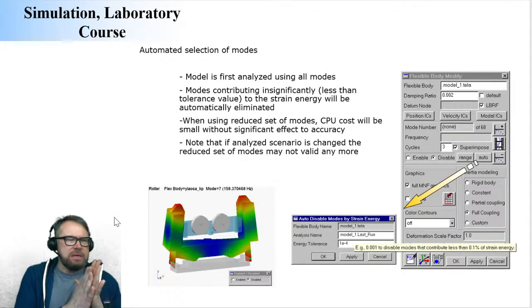Now let's think about that you have used a Craig-Bampton method. In the Craig-Bampton method, you have computed roughly 100 interface modes and, let's say, 20 static correction modes. So it's going to be a total of 120 modes. What you're going to do then is run your system using the entire work cycle of whatever system or whatever you wanted to analyze, using all these 120 modes.